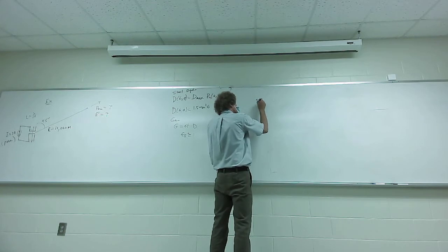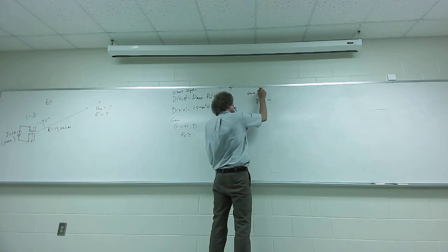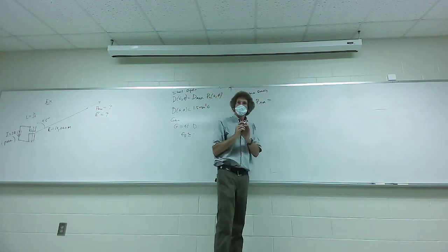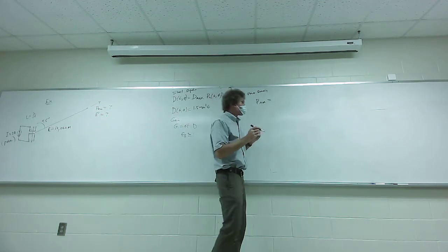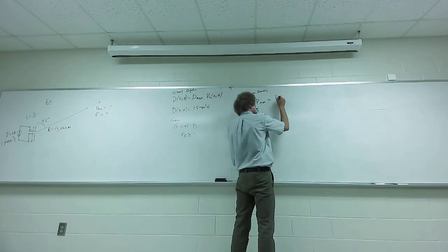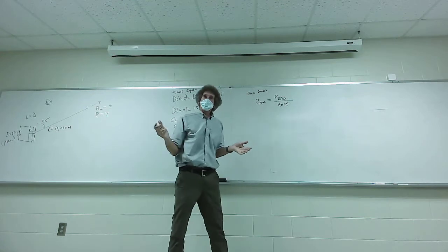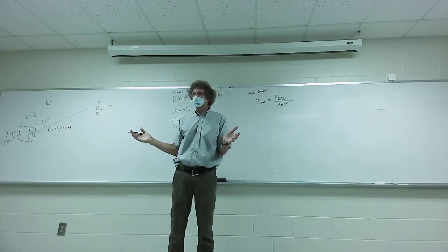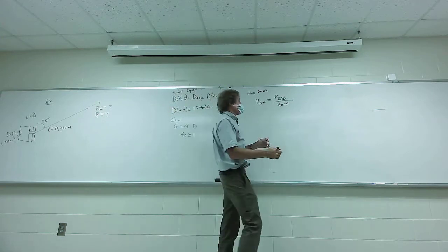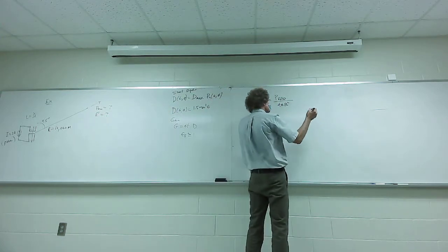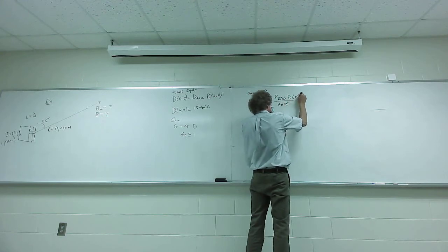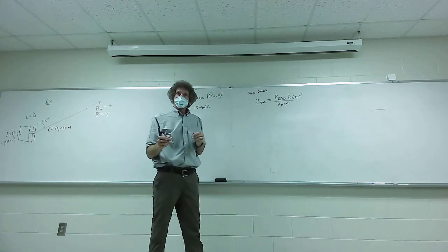The power density, now write this down. This is the power density. For any antenna, if you know the gain, it is the isotropic power density. So I call it P radiation. We take the total power radiated divided by 4 pi r squared. That's what it would be if it was isotropic. Do y'all agree with that? That's no focusing from the antenna. And then we multiply it by the directivity, or gain. Technically the gain, but I'm just going to multiply it by the directivity, of the antenna.